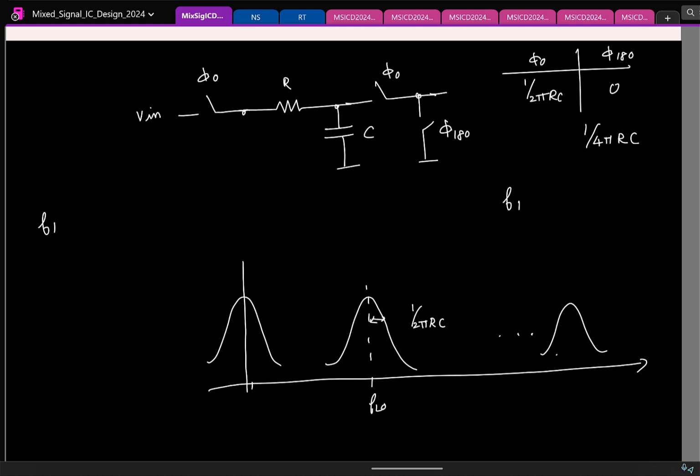So the bandwidth now will actually shrink. And remember, we were trying to make bandpass filters with narrow bandwidth. So is this good news or bad news? Okay. So actually, if you look at this circuit's response, it might be narrow, and the gain is expected to be higher. So the bandwidth will be 1 by 4 pi RC.